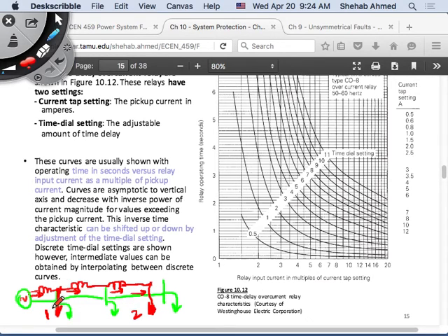So if it's higher fault current, do you want it to disconnect faster or slower? If it's high fault current, you would like to disconnect it fast, right? Ideally, as soon as I see a fault current, disconnect, right? Here I have a breaker, for example. Open up this breaker. That's what you would like to see. But let's say the fault happens at 2. At 2 I would see less fault current because of these impedances in the path. So I would put a device.